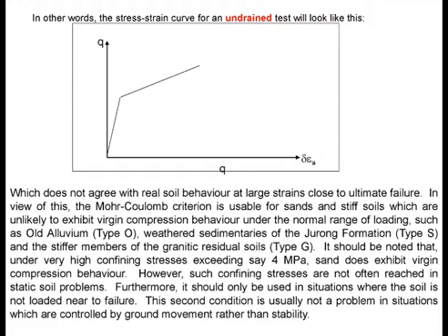Because if you allow the stress to keep increasing to a very high level, obviously your prediction will be unrealistic. But within a certain limited range, your prediction may be okay. So it depends on how you use it. There may be certain materials that dilate very strongly over a short range. That is fine, as long as you don't exceed the strain level where the dilation starts to drop. Is that okay?